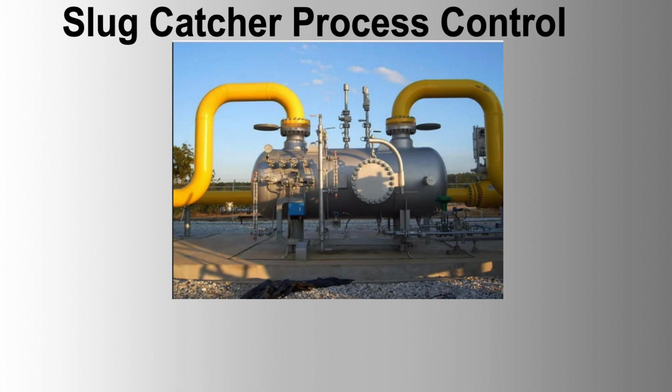Use a feed-forward controller to adjust the inlet valves based on the combined flow rate from well clusters, and a feedback controller to fine-tune the inlet valves based on real-time inlet flow data. 2. Feed-forward and feedback gas pressure control.